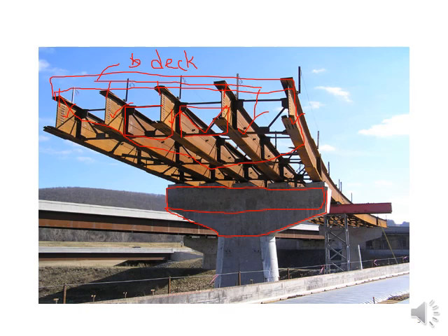Your girders are spanned between these piers. Below the transom you can see the piers of this bridge, or columns, the vertical components responsible for carrying the load from the superstructure to the foundation of the bridge. Here you can see the second pier, and the laterally placed transom. Your stringers transfer their load from this contact point on the transom, and the transom is responsible for transferring the load towards the piers from all sides, and from the piers the load is transferred to the foundation.